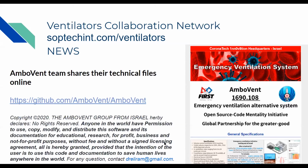So I don't know that an Arduino board is going to be laid out with enough consideration for crosstalk among the channels on your inputs. That would be found out during testing. So obviously most ventilators are not designed around existing boards for other purposes. They have a board built specific, which in our business as well, we have to build our board specific because we have the same problem. So you can test. I'm not saying the Arduino board will not work, but it wasn't designed with that constraint.